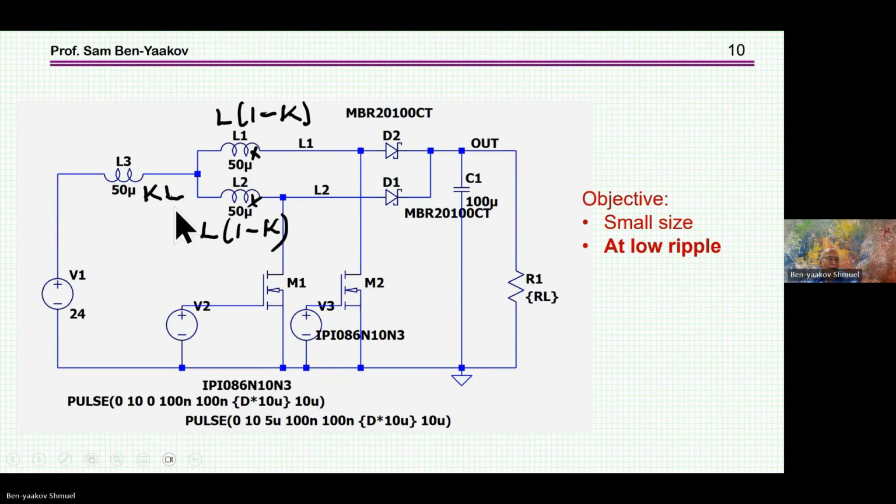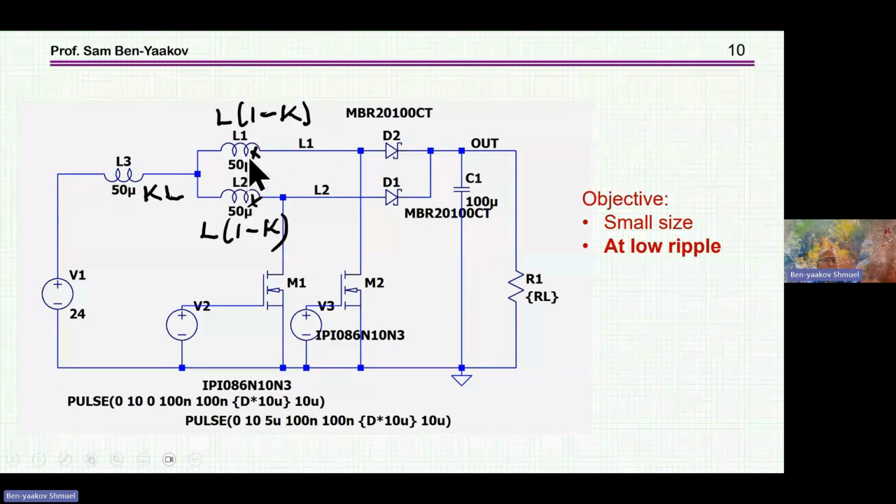Just to get a first impression of what is going on, I've replaced the coupled inductor with the transformer equivalent circuit. These are obviously not coupled, okay? There are dots here which I erased, and this is because LTspice puts the dots on the inductor, but they are not coupled here, okay? So this is like an equivalent circuit of a coupled inductor or a transformer, you might say, with the leakage, and in the transformer way of looking at it, rather than mutual inductance, okay?